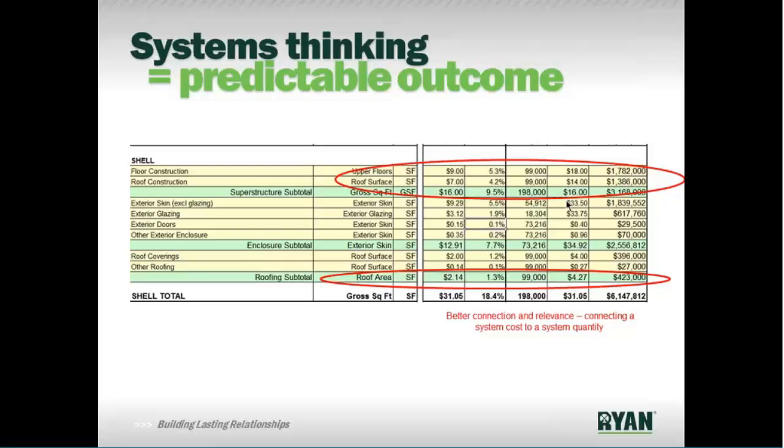The skin system inherently includes a portion of Division 9 drywall, which would be your exterior studs, your exterior sheathing, whatever that is. And you want to capture that as part of your exterior skin system, not part of your interiors. The tendency may be to drop those costs into your interiors, but we're trying to keep those separated so we can gain better understanding of what that skin system is as a whole.